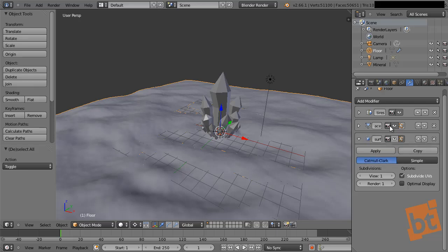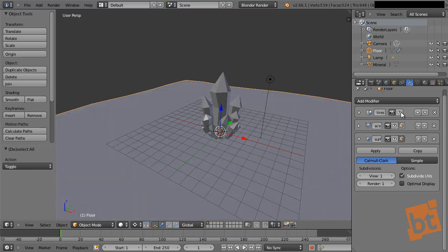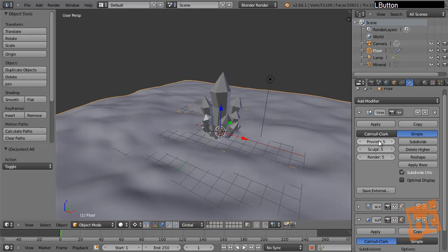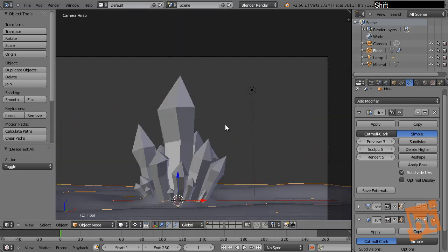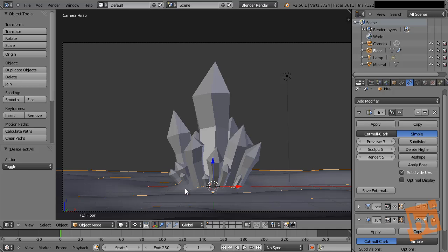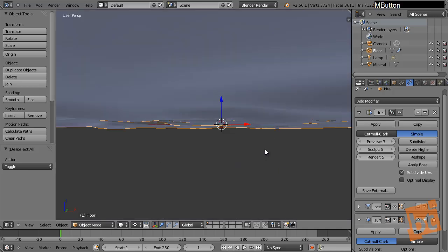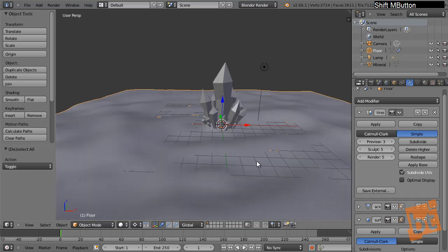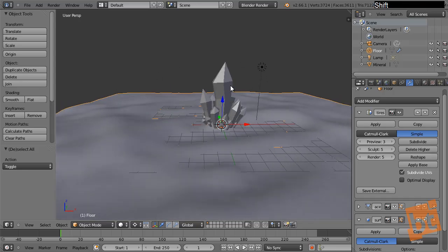Okay, and with the displace also, don't show it in the viewer, and the multires also, well, show it, but here we can set that the render will be level 5, but the preview could be level 3, because this one affects us a lot for seeing how everything works, but it will be a lot faster to refresh in the view to work in real time.